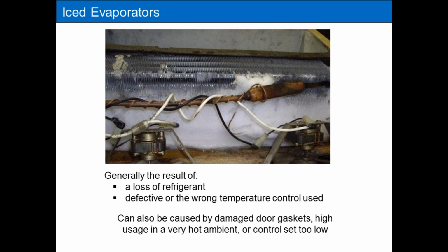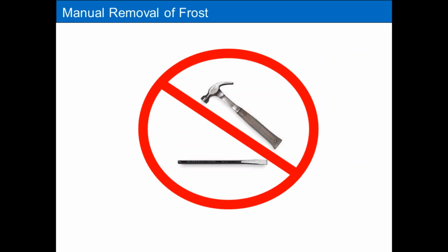So you have an iced evaporator, you have to decide whether it's a loss of charge, temperature control issue, or just high ambient or bad gaskets. So the first step is you got to start with a clean evaporator, so you're going to have to defrost the evaporator. Can't troubleshoot it with a frozen evaporator in place. So first things first, get rid of the ice.